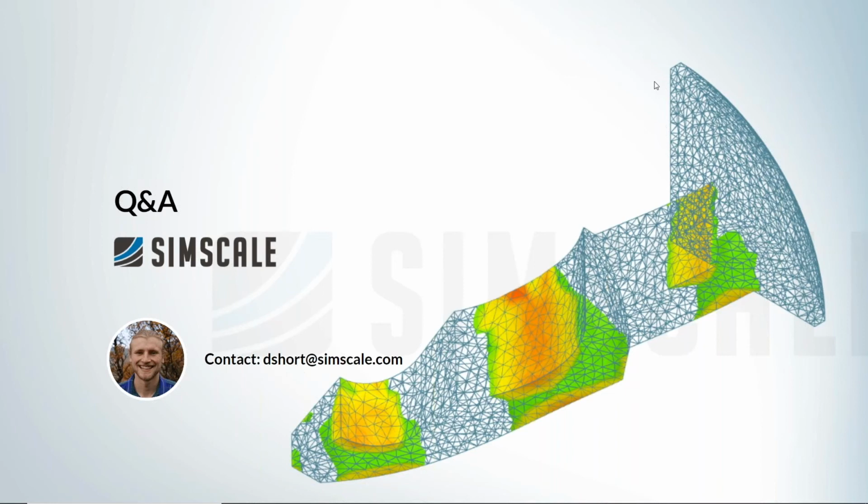So where I would take this next is add some design alterations. Maybe add some fillets up at the connection between the head and the actual wing, and that would allow for a little less stress concentration up there, a little less plastic deformation, and then we take it through another design iteration to see how that performs on a second run.